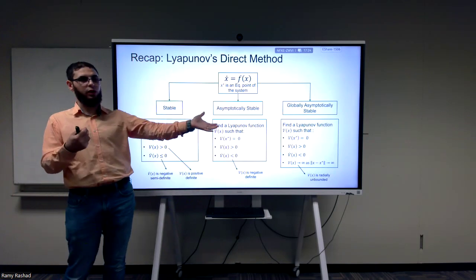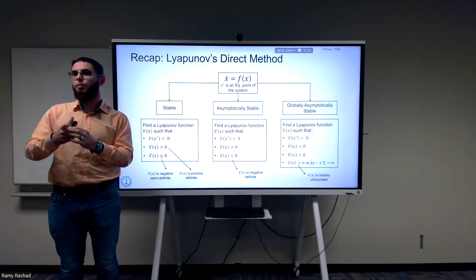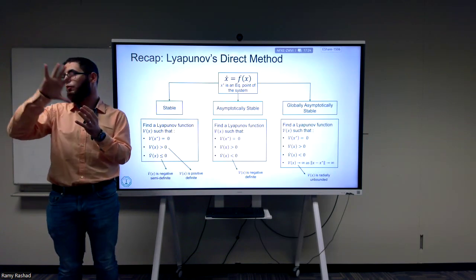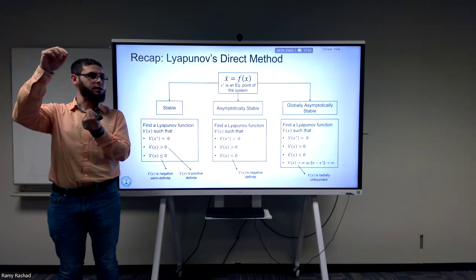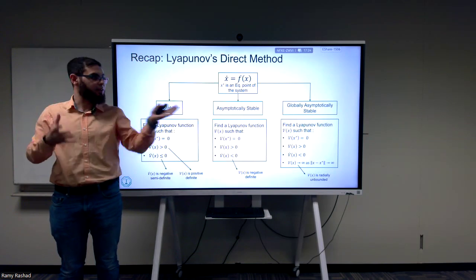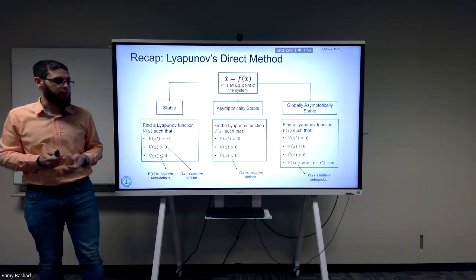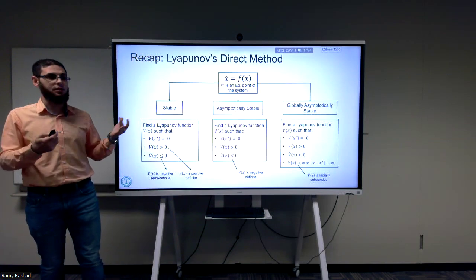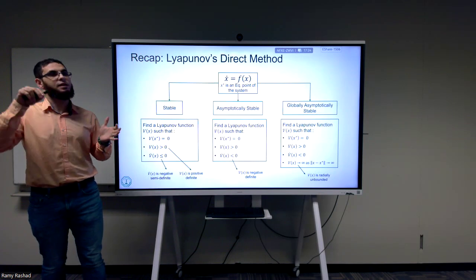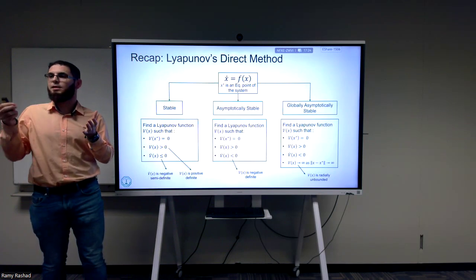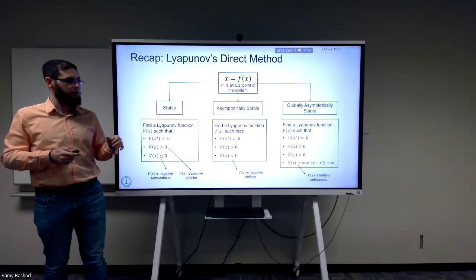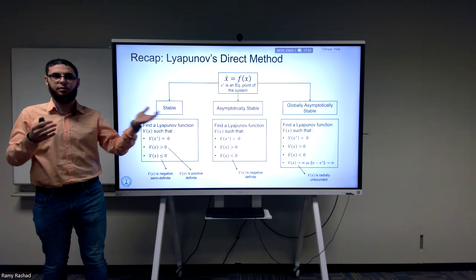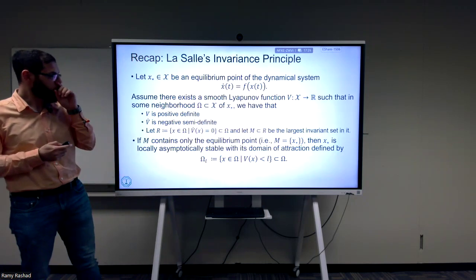You already saw that from the pendulum, right? The topology of the pendulum says the configuration manifold is S1, so we have 2 points that are already there that prevent us from having this global asymptotic stability. The same for S2, and in general, even for SO3, we don't have this global asymptotic stability. But we can have the next best thing, which is almost global asymptotic stability, provided that we can prove that the rest of the equilibrium points are unstable, except the one that we're interested in.